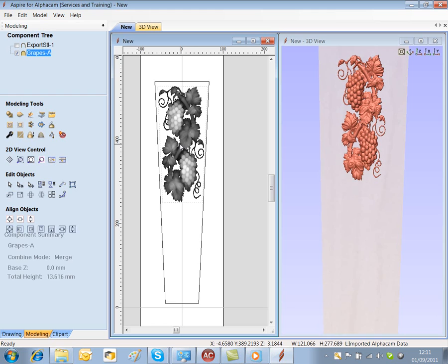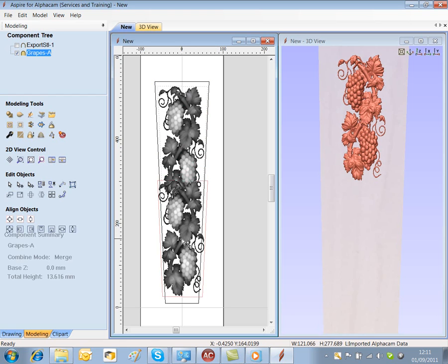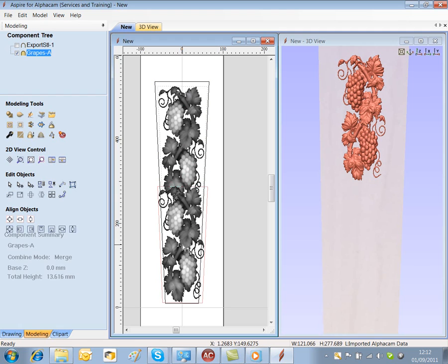Now I want to do a copy of this and bring it down below. So I hold Shift and Control. Shift and Control, I can then drag that down. The Control gives me a copy, and the Shift allows it to come down vertically. So we'll accept that.